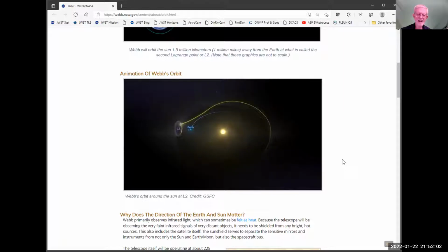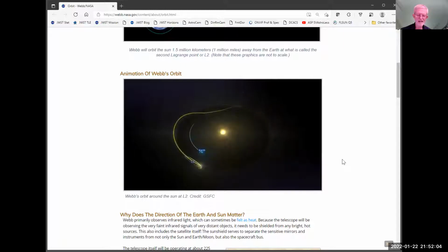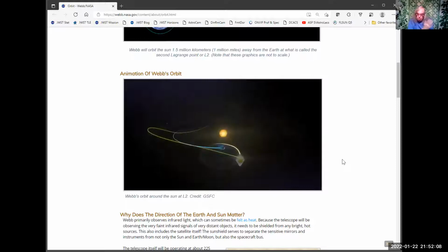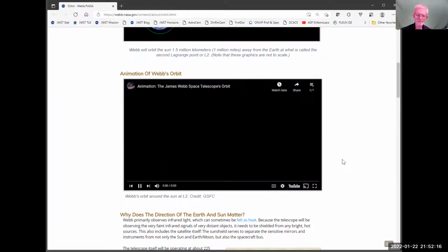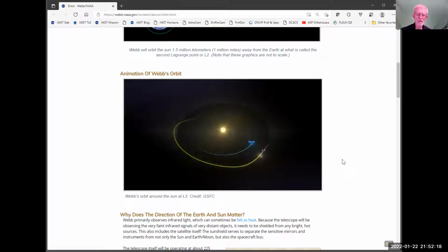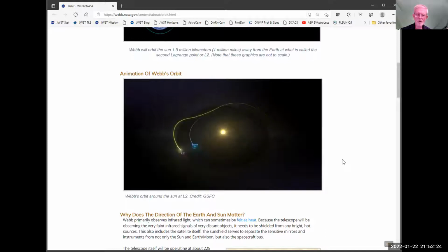No, I have my doubts about fuel, because they have a fixed amount of fuel. Yeah. And they can't do everything with the momentum wheels, and they positively need the fuel to shape the elliptical orbit about L2, because it's not a stable orbit. So they will be periodically consuming a continuous amount of fuel. And when that fuel tank starts to run low, you're done.